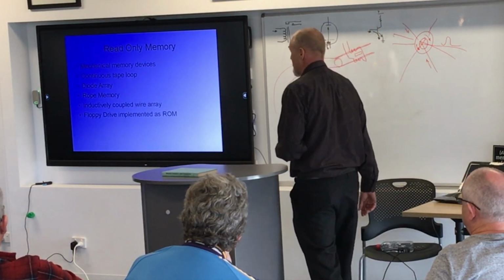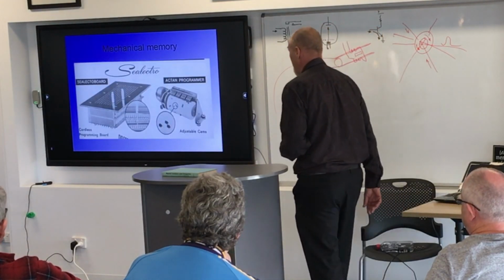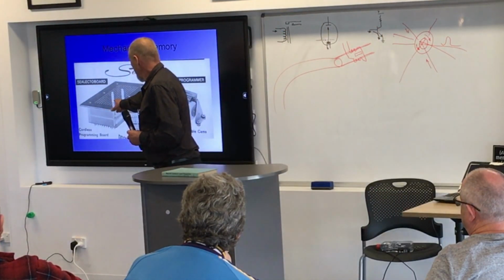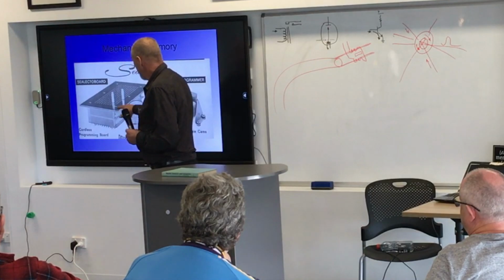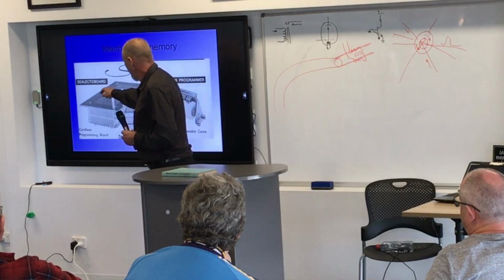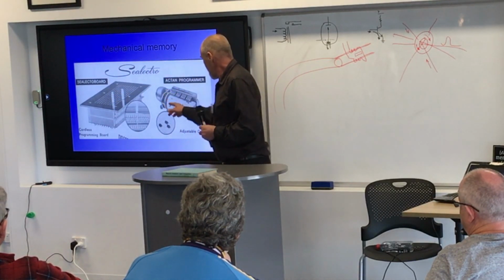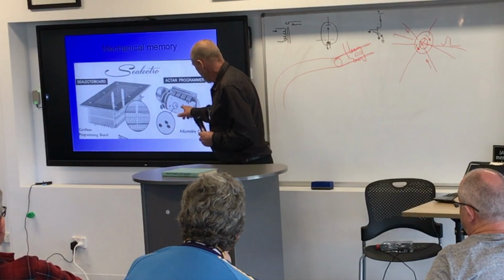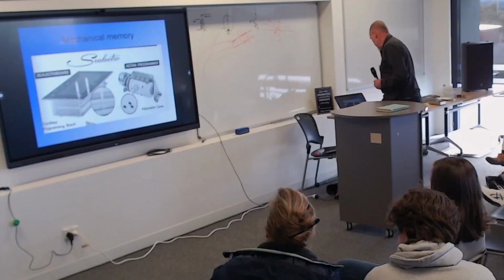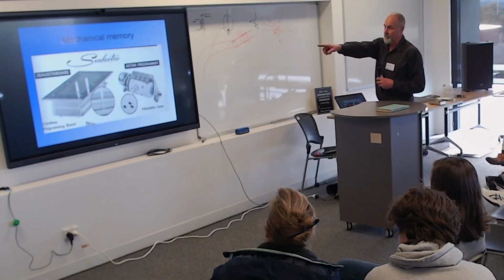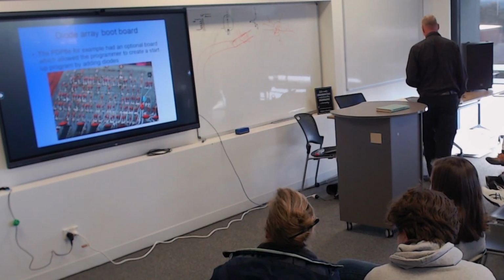Now, read-only memory. My goodness, there are some crazy things out there. First thing is a diode array where you can just put pins in and there's a little diode inside here. I could write a boot code by just placing pins in here and boot a PDP-8 using one of them. Or I could have a little motor drive and a bunch of inserts in here and write a program on a mechanical device to boot a computer. So yeah, read-only memory, programmable, that's a PROM. That's PROM as well, I guess. Diode array boot board.